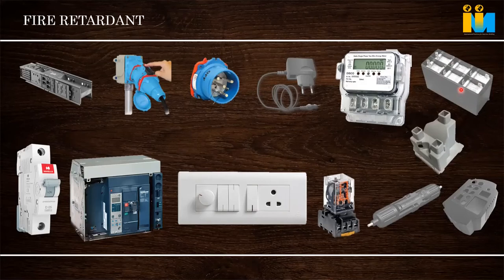Generally, many manufacturers compound it themselves, because it's a cost-sensitive market. They buy normal PP and fire retardant, and compound based on their application, and together they compound the color also. Some are dark, green color, red color. You have seen bigger players in the market. Based on that application, the amount of fire retardant you require is added and compounded.